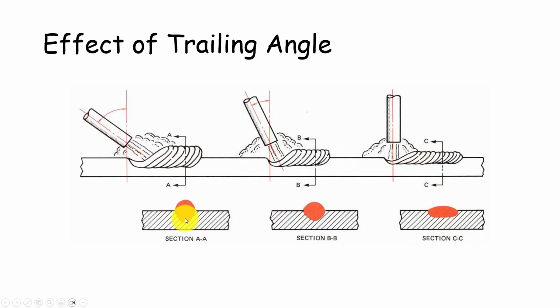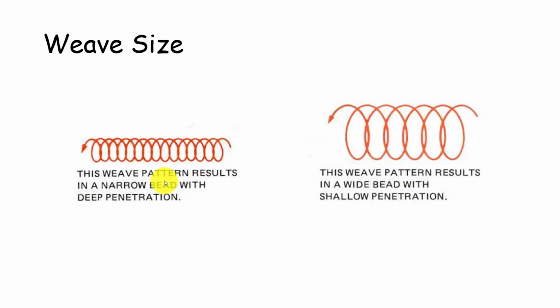Likewise, the trailing angle, we can really get some more depth on the angle on here. And again, the weld's going to push up and stack up a little bit more. So a welder is going to know how to do those kinds of things and be trained in it. Another thing they're going to do is learn how to do different kinds of patterns.